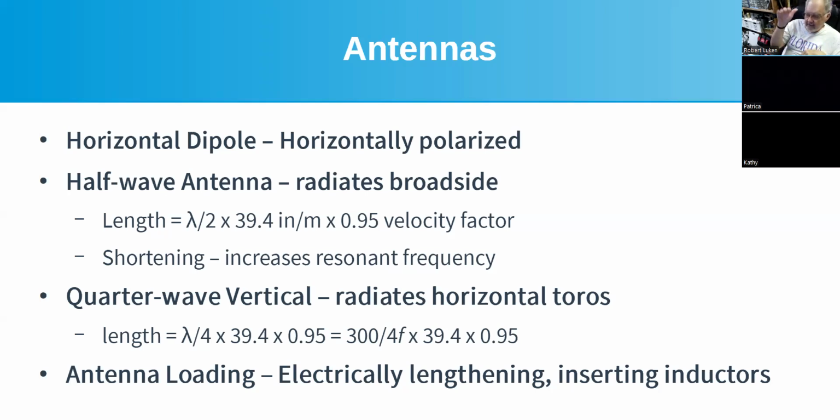It allows you to make the length of your antenna much shorter, but it's a compromised antenna. Actually, the only part that radiates is the vertical section, not the inductor itself. So you lose gain on the antenna when you do that, at the expense of having a very long antenna sticking up on your vehicle.